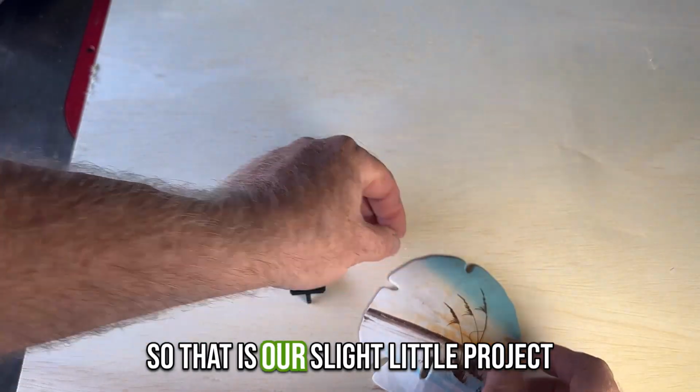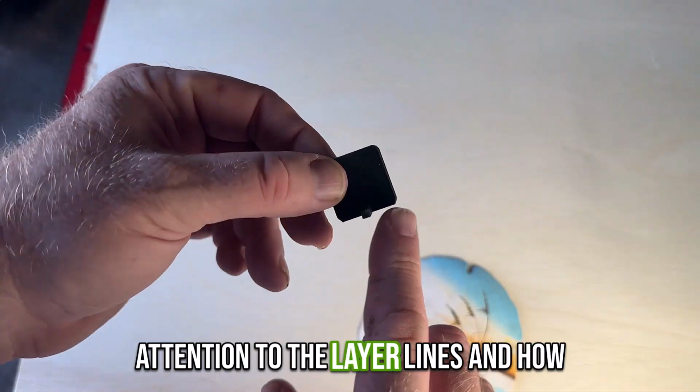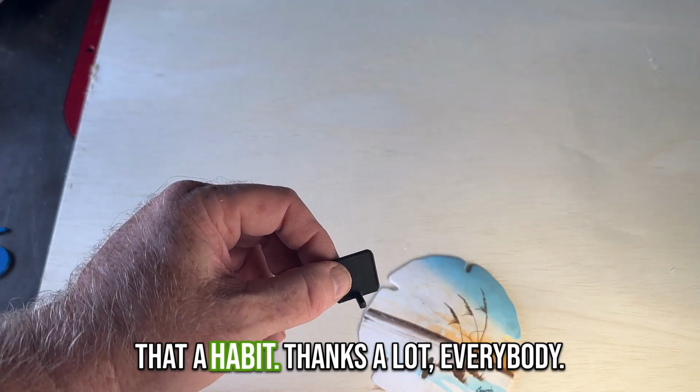So that is our little project for today. And again, the main thing we're trying to cover here is to pay attention to the layer lines and how everything is oriented when you print it so that it comes out as strong as possible, and just make that a habit.